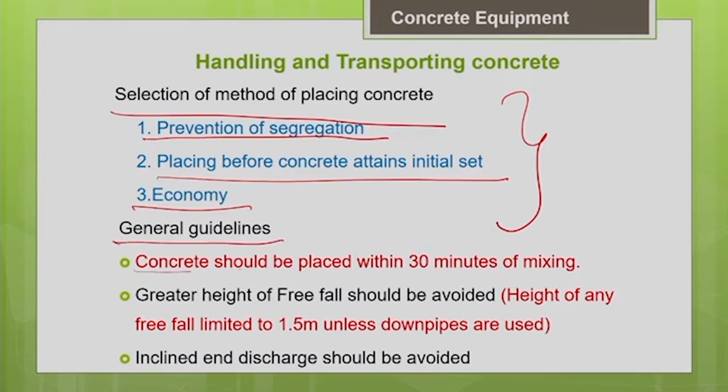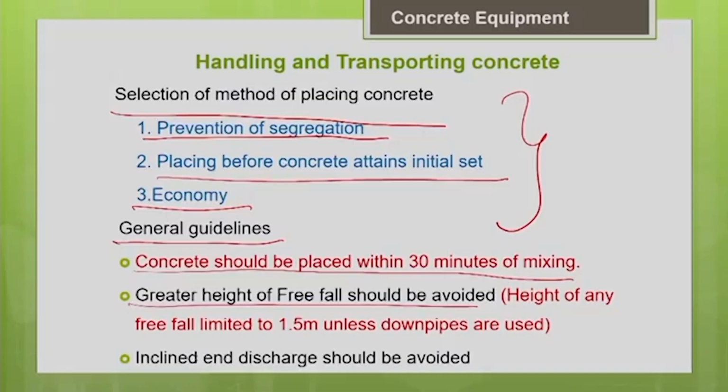As I told you, concrete should be placed within 30 minutes of mixing, before it attains the initial set. And we should avoid a greater height of free fall of the concrete. You should not allow the concrete to freely fall over a greater height, as that will result in segregation. The maximum free fall height allowed is only 1.5 meters. Free fall means there is no support at all, you are just freely allowing the concrete to fall from a particular height.